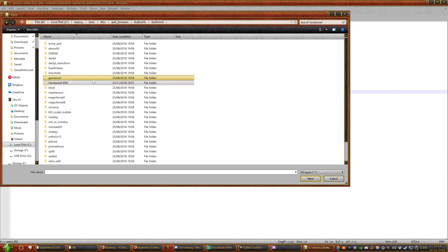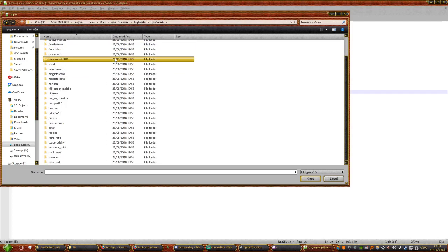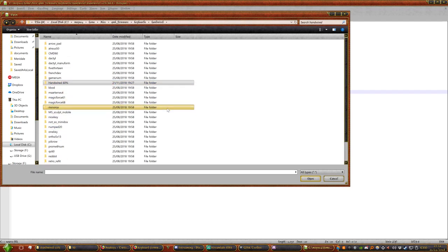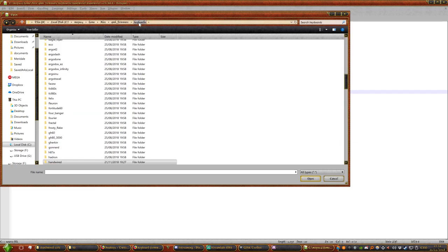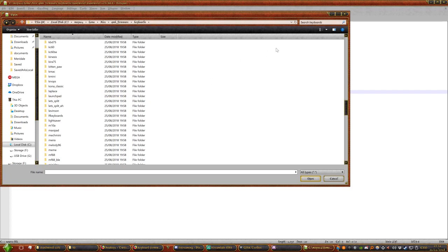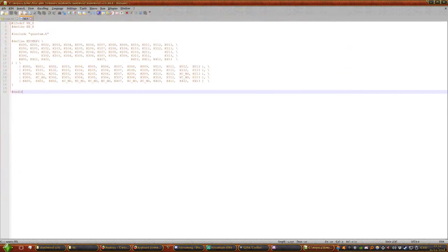So is that down here? That might not be down here, because I think that's on a different part. But anyway, you notice that on my UK78 I have a separate numpad that's separate to the main board. So electrically we'll see that numpad separately to the rows and columns, but you can define the keymap to have the numpad continue along your actual physical rows and columns, despite it not continuing on the electrical rows and columns.